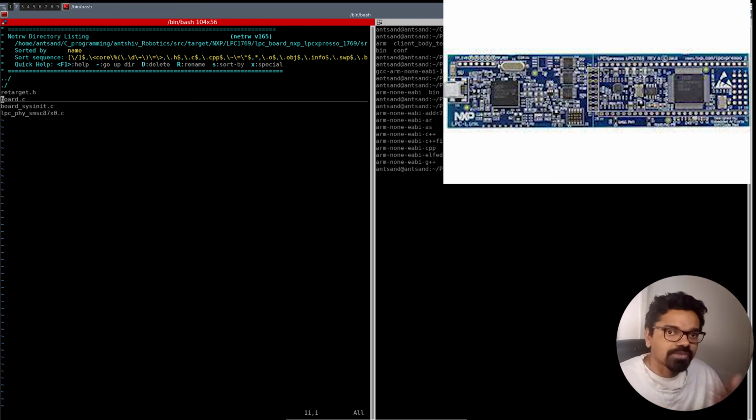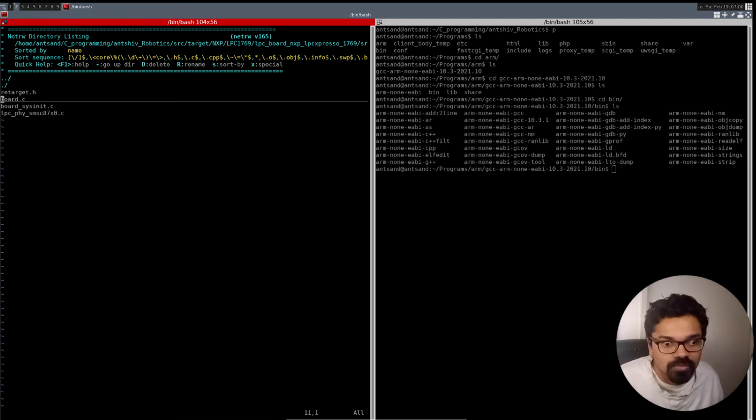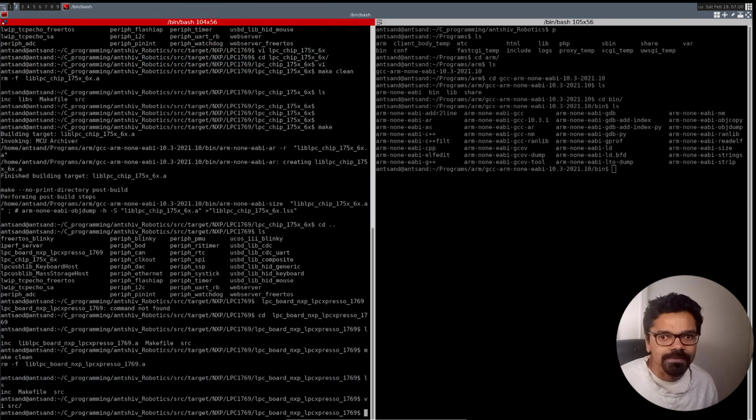Whereas you're just creating an abstraction of saying, okay, now this particular board has certain pins connected to certain parts and certain peripherals. Let's get those activated. That's really what it's doing. Like if you have an LED, which part of which blinky is going to work? You want that blinky on port C, pin number 3. Those are the kind of things that this particular folder has. So let's compile this.